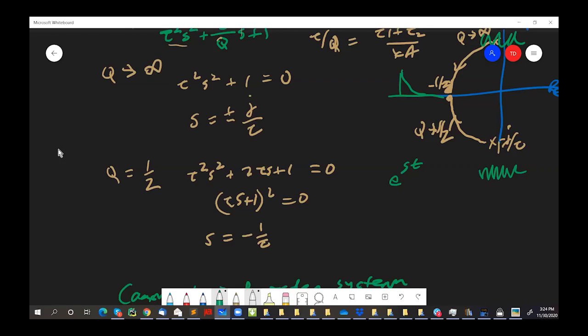And so it describes how stable the response is to a disturbance. Because remember, this is the natural response. If you kick the system, like capacitively coupled to it, and kick it, how does it respond? Does it come back like a pure exponential? Does it ring a bunch of times? And it turns out that Q is a quality factor, approximately the number of cycles of ringing. So if you can extract Q from your transfer function, then you can basically say how stable the system is. Is it going to ring, or is it just going to nicely approach the final value?